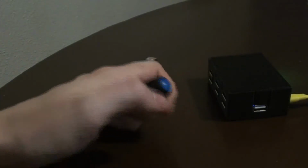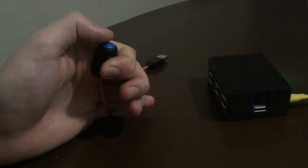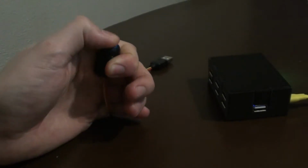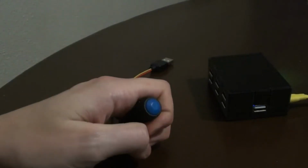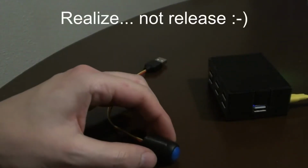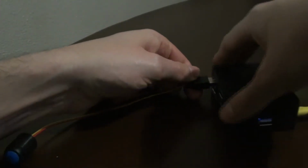So what we have here is a very simple input button. As you can see, just a standard push button, a momentary button, meaning that it will register the status as being pressed as long as you hold it down. The moment you release it, the microcontroller will register that the button is free again. So to demonstrate this, we're going to plug our button into D1, for example.